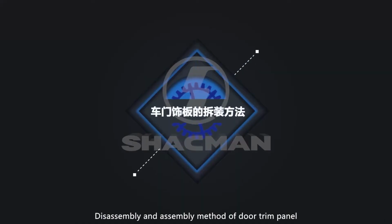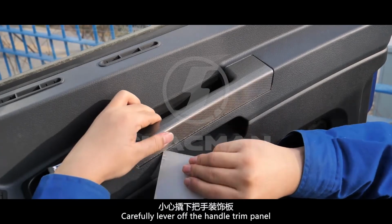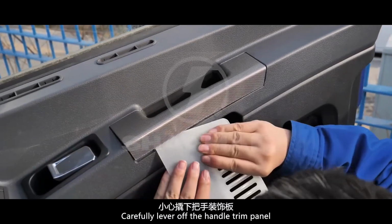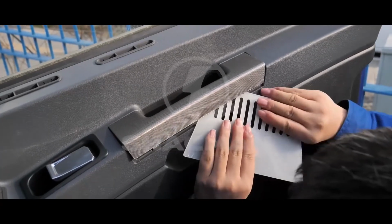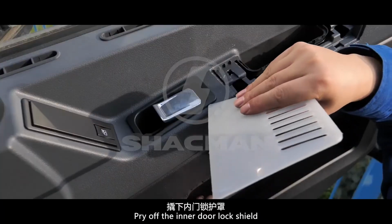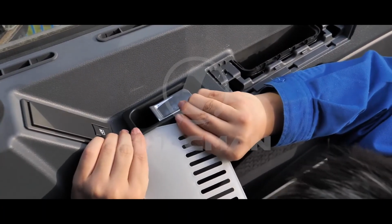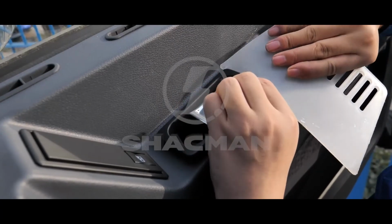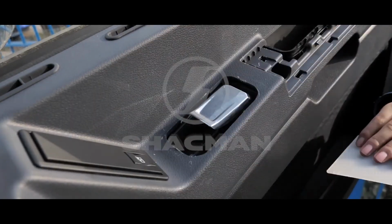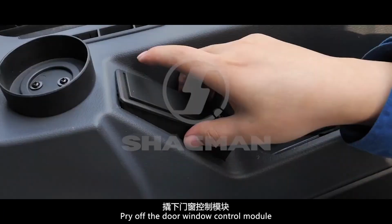Disassembly and assembly method of door trim panel. Carefully lever off the handle trim panel. Pry off the inner door lock shield. Pry off the door window control module.